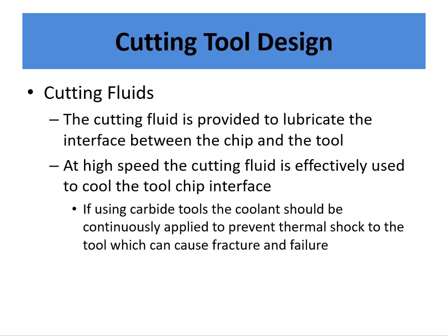So cutting fluids. Your book is going to talk a lot about cutting fluids, so please read about all that. Generally, think of cutting fluids as a way to lubricate the interface between the chip and the tool, and to reduce heat loading. Also, one thing to remember is if you're using coolant, usually you want to keep the coolant either on or off. It's not good to do intermittent coolant, because you can cause thermal shocking and then you get cracking.